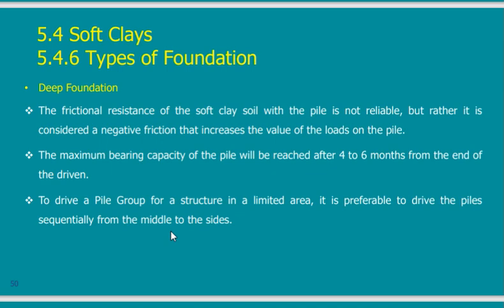You make a fence around your site. Water will not be free to leave. And then when you try to put your piles inside, you will face a problem. Water cannot move. But it is better that you start from one direction, put your piles. Every time you push your pile, it pushes the water in one direction, and so on, continue in the same direction. So finally you put all of your piles and you end up having water outside.